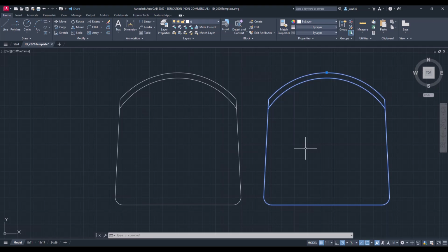And I feel like that's a good thing, because once exploded and you want to reblock it, you have to go through the entire blocking process again. So if you need to make a change to a block, use the block editor. And if you really just need the object to go back to lines so that you can update a specific instance of that block, or for whatever reason, go ahead and use the explode. That's all I have to show you in this video.